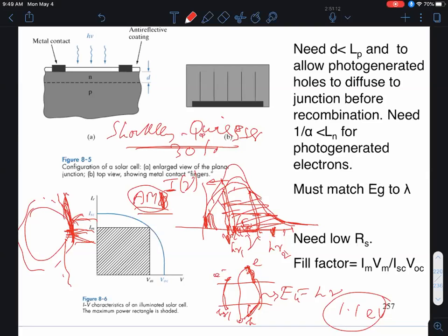At sunrise or sunset, I'll obviously get a lower solar intensity. So what's done is, typically when you characterize the solar cells, you assume some sort of an average, say, at maybe 9 o'clock or 3 o'clock, and you assume an air mass of 1.5. Okay, so that's not the best case, not the worst case, and you look at the solar intensity profile at air mass 1.5. So if you read the literature, that's what the terminology means, okay?